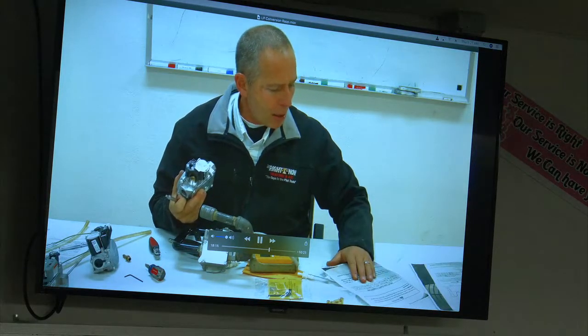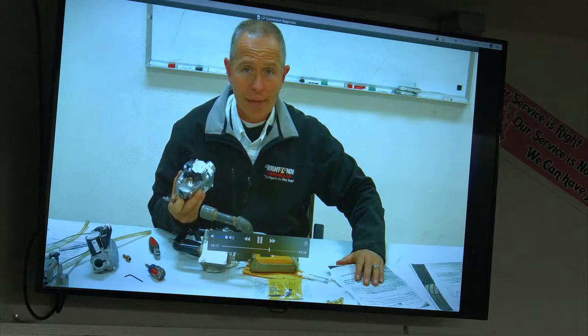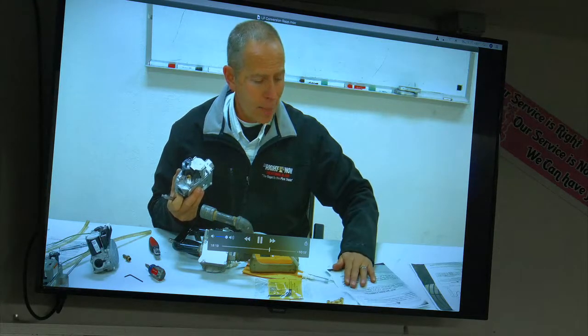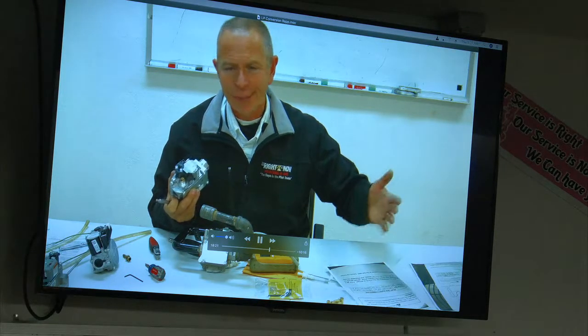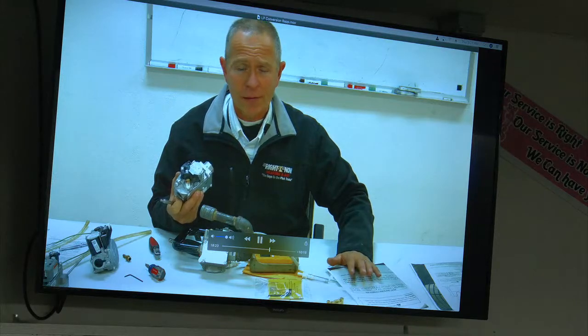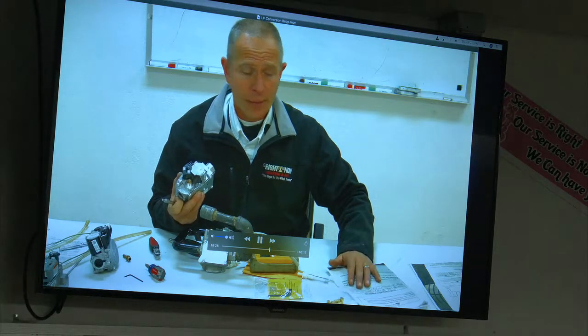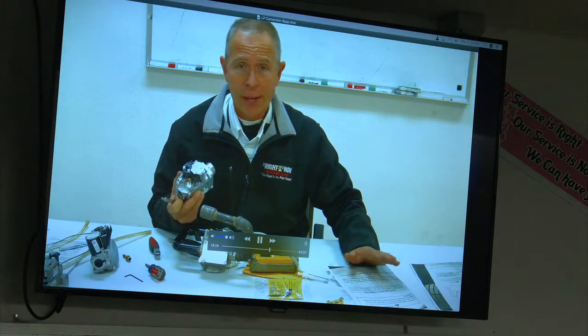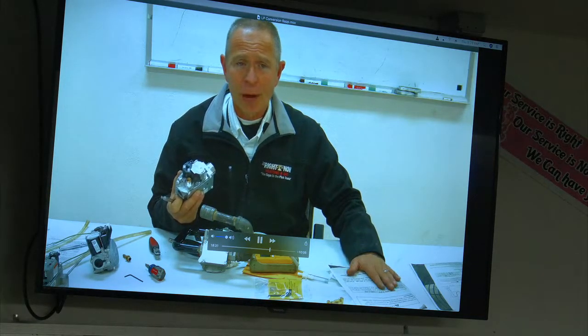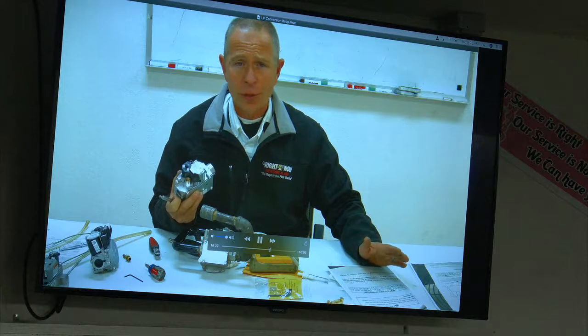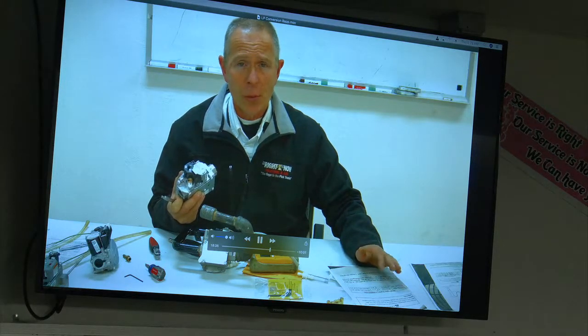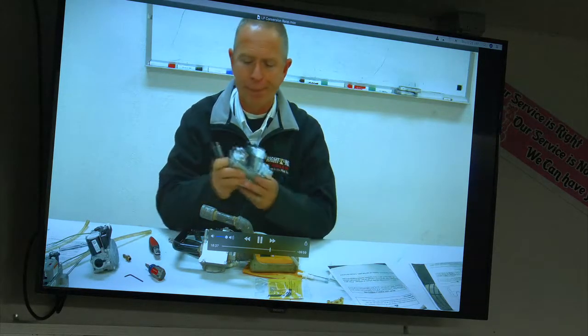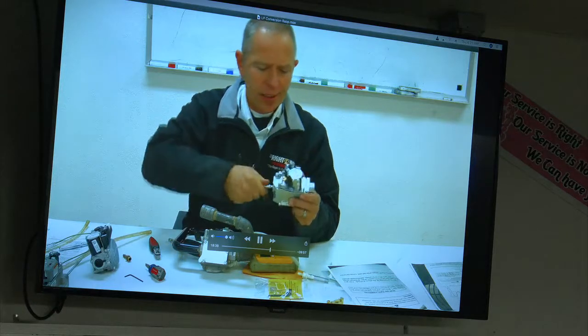So once you do the inlet, again, that's going to be the same settings. For propane, our minimum is going to be 11 inches of water column, and our maximum is going to be 13. It can go up to 15, but as long as it's not like 20 or something way off the charts, it's going to operate just fine. But we want to make sure that it does not drop below the minimum, and it really shouldn't drop more than 2 inches with full consumption of that.